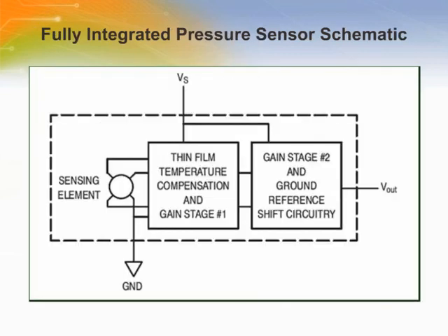To make the designer's job even easier, Freescale's integrated devices carry sensor technology one step further. In addition to the on-chip temperature compensation and calibration offered currently on the 2000 series, amplifier signal conditioning has been integrated on-chip in the 4000, 5000, and 6000 series to allow interface directly to any microcontroller with an onboard analog-to-digital converter.